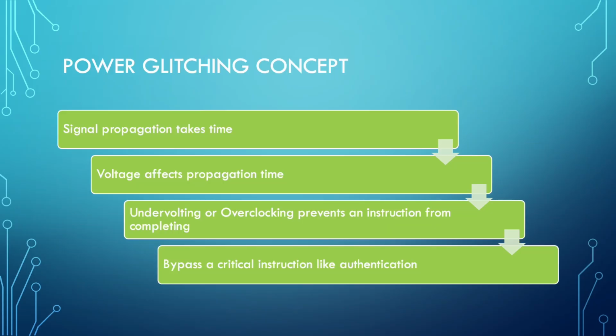In an introductory circuits class, it's common to assume that signals propagate through logic gates instantly. In the real world, this takes time, even though it's seemingly instant from an end-user perspective. The time it takes for a signal to propagate depends partly on the voltage. We can use higher voltage to force the signal through more quickly, but this increases power consumption and heat generation.